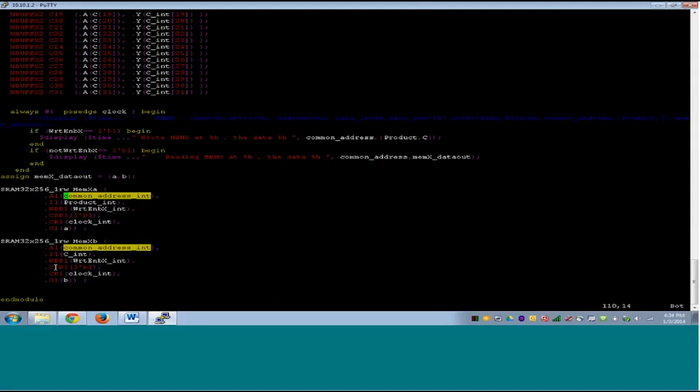Usually what happens with memories is that we have to make sure that the transitions at the inputs and outputs of these memories are very good. So it's good practice to have explicit buffers and tell the layout engineer to please make sure that these buffers are placed close to the memory address. That way you are making sure that the transition numbers are good.